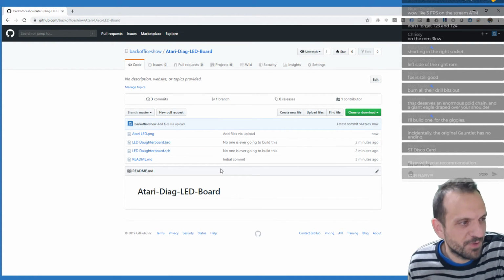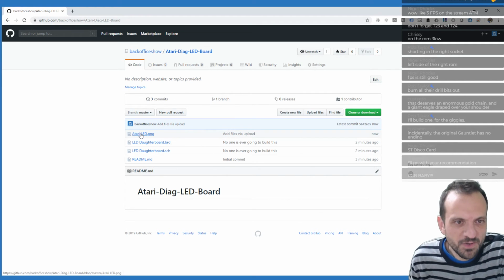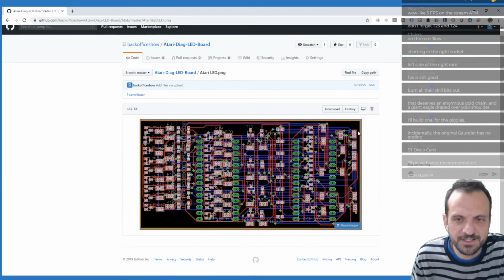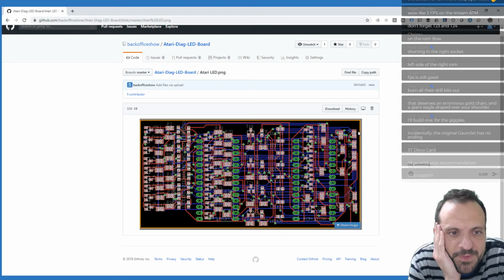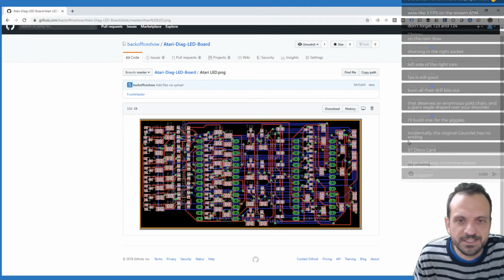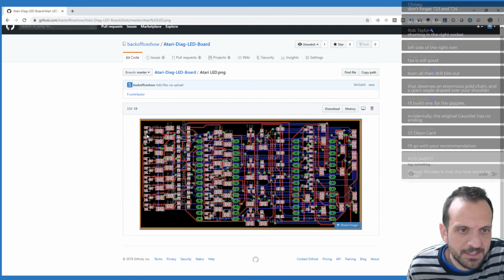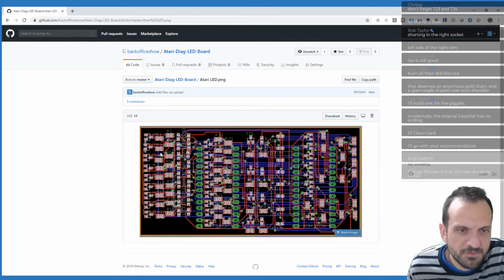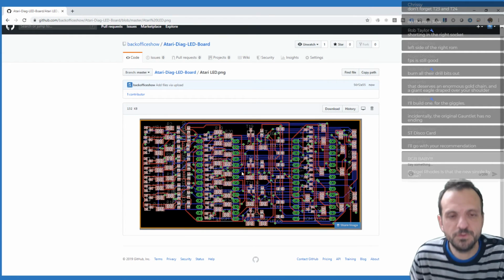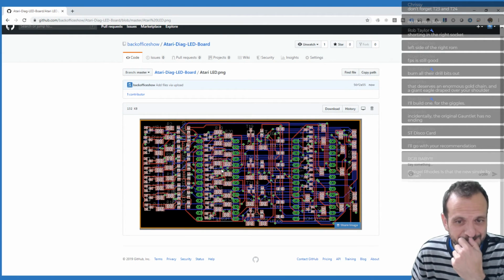Yeah, you'll go with my recommendation of not building it. No, I think it will work. I didn't check the DRC, right? But I can't see any real reason that it shouldn't work. It's just make sure when you make it, if you get it made, just get the wires tented, because some of the wires are pretty close and they might short if you try to, it's a bit fiddly and you might just short them out.